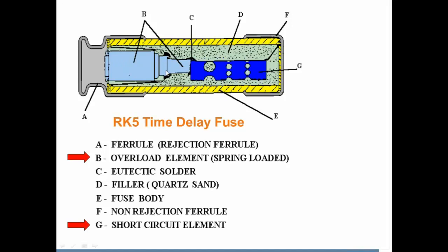As a result, if you have an overload, this will open this section, and if you have a short circuit, this will open without any time delay. Well, when we say time delay, we are talking about seconds. When we are talking about short circuit instantaneous, we are talking about fractions of a cycle.